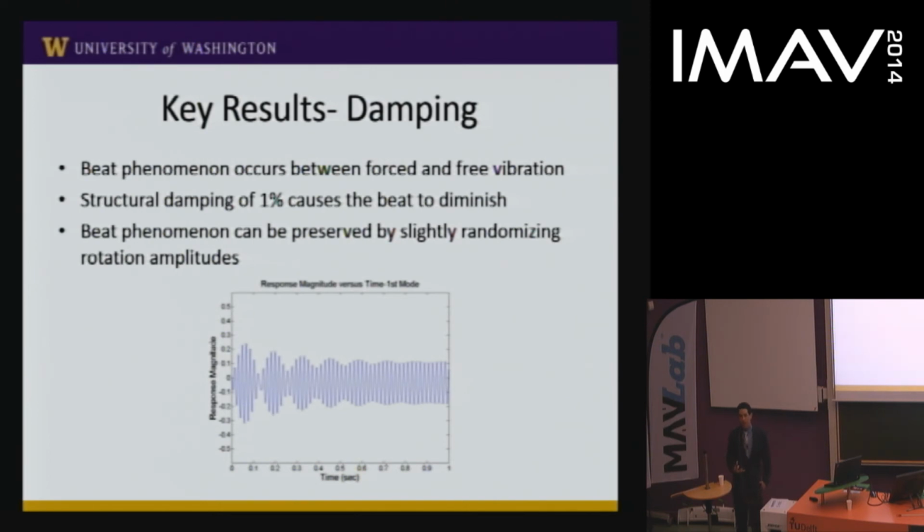So really, to test this hypothesis, we've introduced a modal damping of about 1% and solved the equation of motion numerically, just to see what result we got. And of course, you can see based off of this figure, the beat becomes indistinguishable within 1 second, which of course is problematic to our hypothesis.